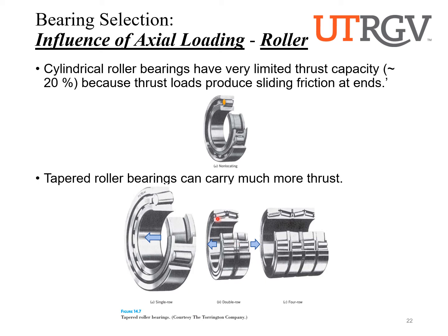Each of the rolling elements oriented at the angles is going to take the loads in one direction and the other, right? And you can do so to limit the axial loads in both directions. Now, if you can't get a bearing that is good enough size to support those axial loads, we can double up on those, so we can stack them until we have enough capacity to keep that shaft from moving sideways or destroying the bearings.